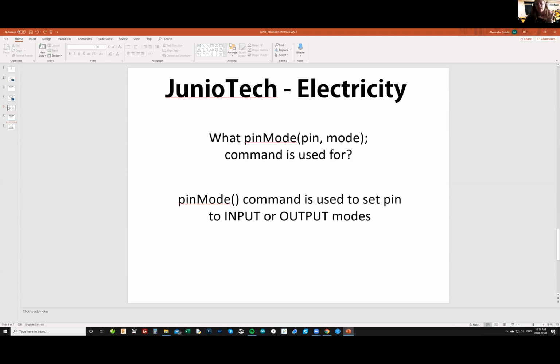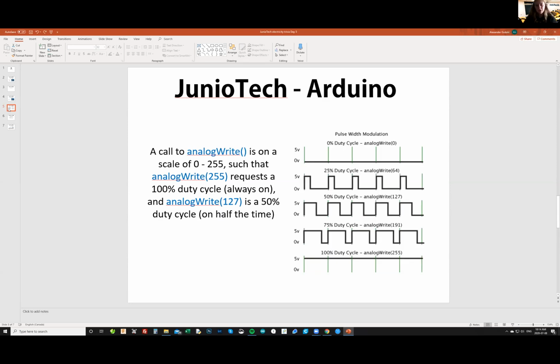So Alex, really quick, let's go back to that for a second. Just to make sure everybody understands, if I have a light bulb hooked up to it, what will be the difference between, for example, 255 and 127? Does anyone know? What does this mean? I do. Yeah? What does it mean? Basically, 255 will be a little brighter than 127. Yeah? Twice as bright, actually. 127 is about halfway between 0 and 255.